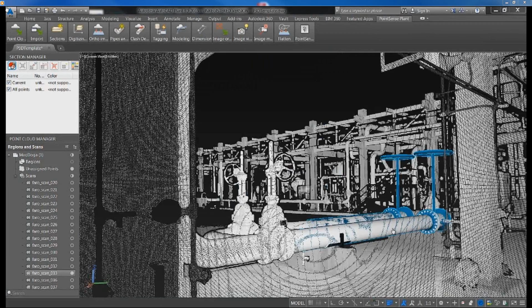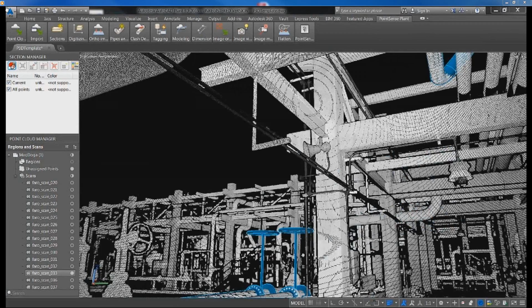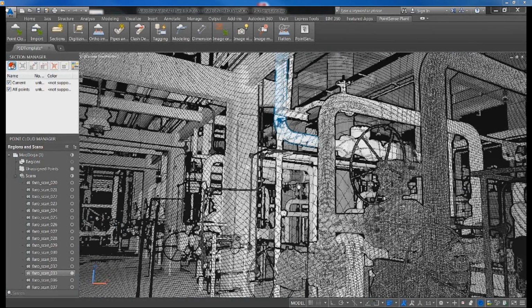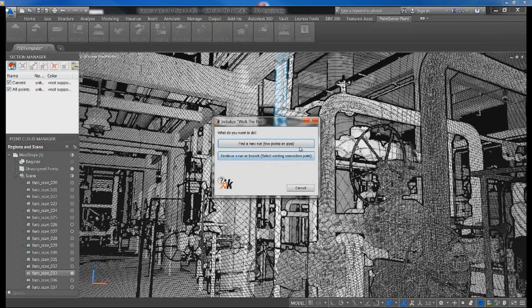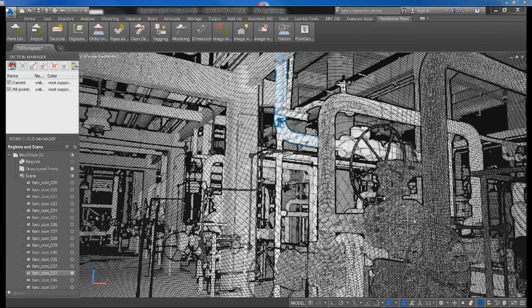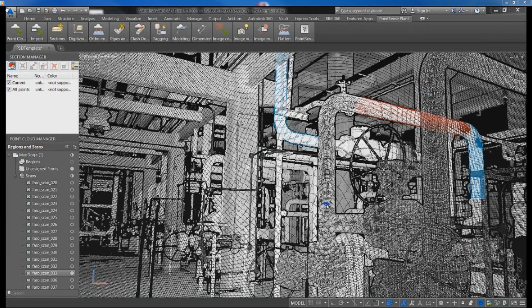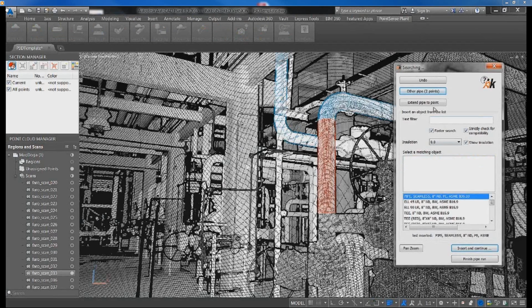And I'd like to go ahead and run just a couple more here. And the reason for this is I want to have a nice sort of complex line to do for the export Plant 3D. Now you can export everything at once, but I want to show this one line so I can generate a nice isometric for you. And you can see all I have to do is 2 points, no welds, or don't worry about the ends. And then here at the T, same sort of thing, except I'm just clicking points on the branch piping.